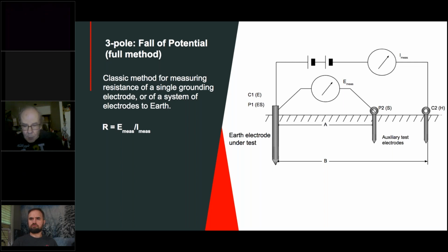And so then the potential probe, which the operator typically manipulates, is going to be established in the ground at critical distances, and measurements are going to be taken. And what you're measuring now is the potential drop to the potential probe caused by the resistance of the intervening earth. So now you're seeing on your display the resistance to wherever the operator placed that potential probe. Next.